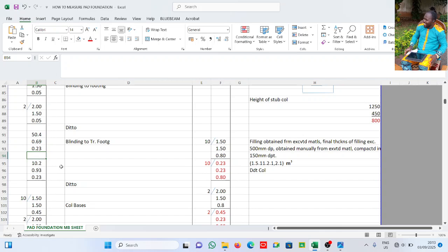And if you can see, I am not squaring. What it simply means is I'm not preparing any bill of quantity. The same thing if it's an exam. If you have to prepare a draft bill of quantity in an exam, I've explained that over and over in our previous video, so that I don't keep repeating myself. A draft bill, you don't square your taking off. Your bill does not carry quantity. It does not carry rate. It does not carry amount. It only carries units. That's a draft bill.